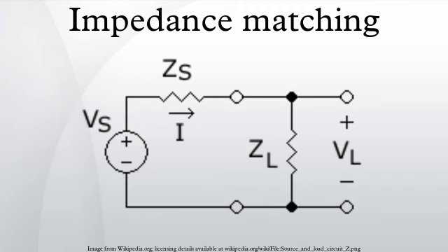Resistive impedance matches are easiest to design and can be achieved with a simple L-pad consisting of two resistors. Power loss is an unavoidable consequence of using resistive networks, and they are only used to transfer line-level signals.